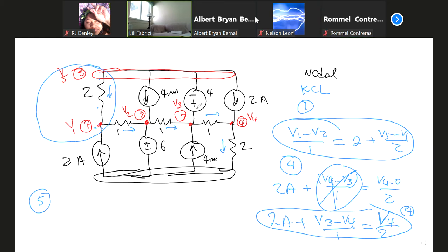Okay, then this voltage source is causing a problem. If it's causing a problem, I have to bypass it. What do you suggest? You create a supernode. Okay, even though it's not face-to-face, can you describe how to draw a supernode to bypass this voltage source?